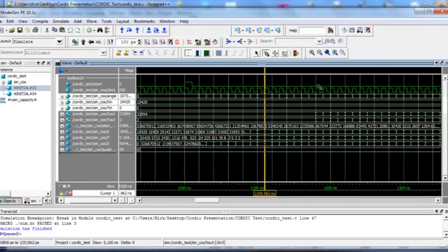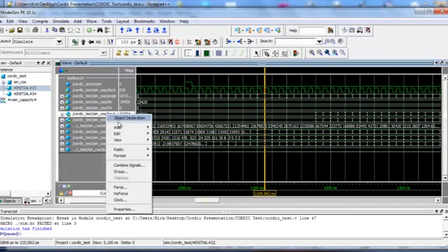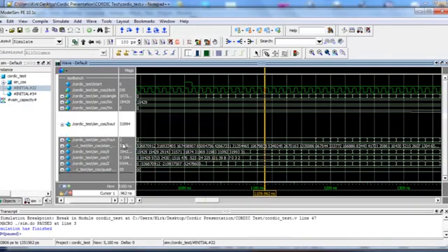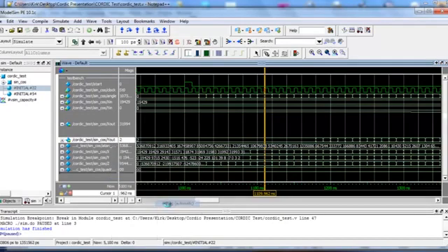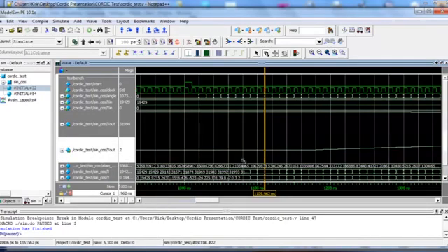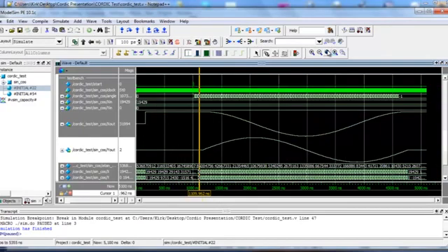So now you could go through and collect all these values. You could maybe stick them in a spreadsheet, compare them with some calculations made in Excel or something like that. But one of the nice features of ModelSim is you can take the outputs, such as the X out and Y out, and change the format to analog and watch what happens. You don't see anything yet. I'll change the other one. Format, analog. Okay, now you'll see it's an analog type signal. So let's zoom so we can see the whole thing. And what do you know? We have sine and cosine functions.